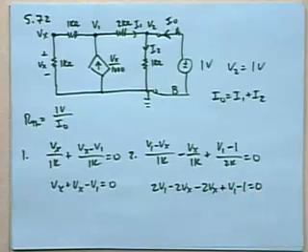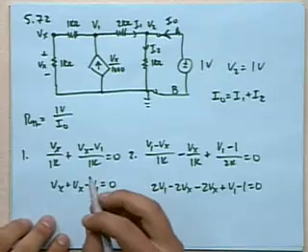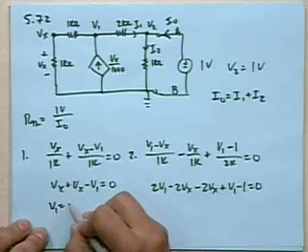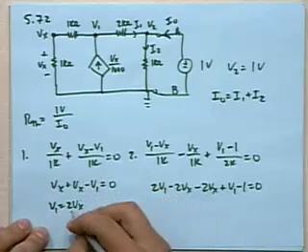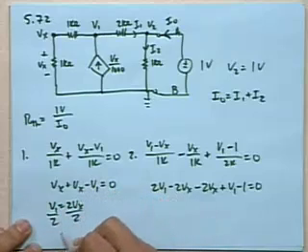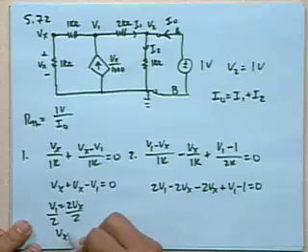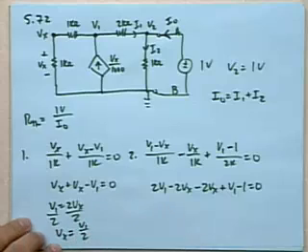One of the things that it probably would not be a good idea to do is just put V1 on the other side. We'd really like to solve this for Vx and get everything in terms of V1, solve more directly for V1, because that's the parameter that we're going to need going forward. So V1 equals 2Vx, so we can divide both sides by 2, and anywhere that we see Vx, we can replace it by V1 over 2.